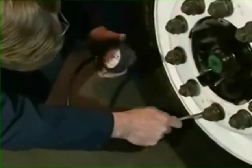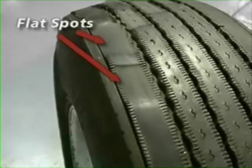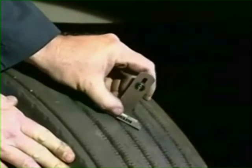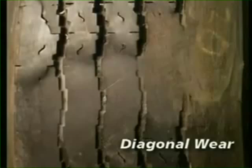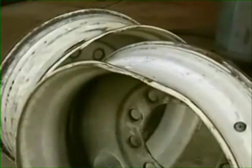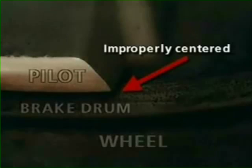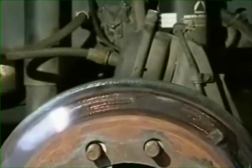Check the front tires for inflation pressures, flat spots, unequal tread depths from side to side, or any mechanical or alignment-induced wear patterns such as diagonal wear. Check for bent wheels, loose lug nuts, or incorrect seating on hub pilots. Check the brake drums for missing weights.